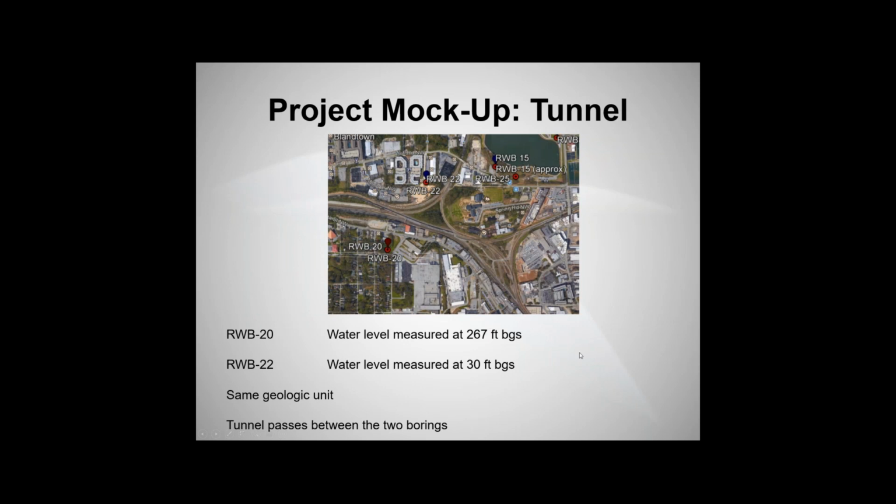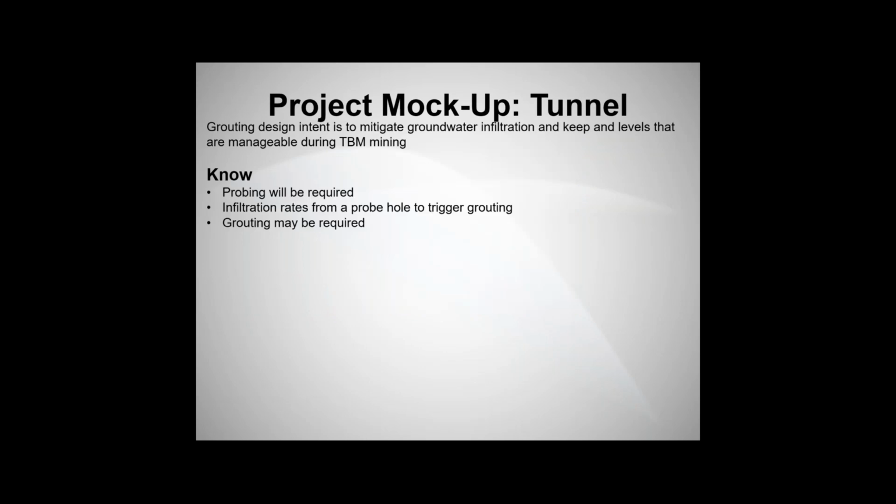I'm not sure what. I don't know what kind of machine they're going to have. I know it's going to be TBM driven, but again, just imagine you're in the early stages of design. There's still a lot you don't know. So you look at this, and again, what's the first thing we do? What's the intent? What are we trying to grout here? We know we have to do something. Well, we know that we've got a very steep gradient, and we're trying to reduce the amount of groundwater infiltration into the tunnel. We want to maintain a safe excavation. We want to keep things manageable during the mining.